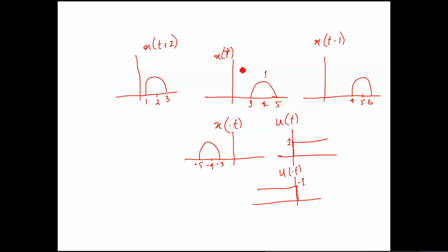Remember this. This duration is past. I think I talked about it earlier also. Remember this throughout in engineering. Once we plot the time axis t here, this denotes the past, this denotes the future, and this denotes where you are right now. So t minus 1 is actually shifting right, t plus 1 is shifting left.